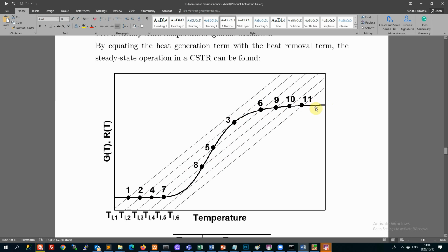And now there's another special value that could arise. So let's say we liked operating up here because we know the temperature is nice and high here and we get nice high reaction rates here. So our inlet temperatures were all in this range. That's at the inlet point, but in the reactor we are operating in these ranges.